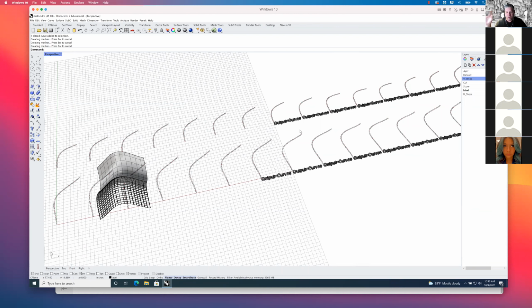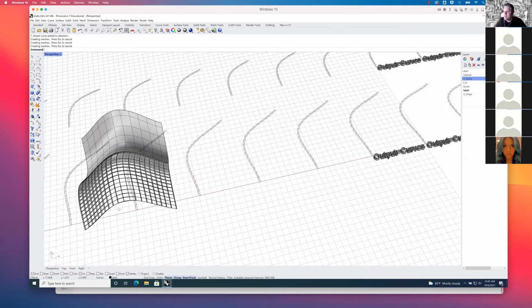And then, here's the thing. When I can generate this in 20 seconds, I can generate lots of different options and evaluate, okay, what thickness do I want? Is this too thick? Is this too thin? Maybe I also play around with the spacing. Maybe 20 by 20, what does that give me? That gives me 400 cells. That means 400 components. Maybe that's too many. Maybe I dial it back and say, okay, let's see what it looks like when I do 10 by 10. That gives me 100. So then I basically cut the amount of components all the way to 25% of what was there before.